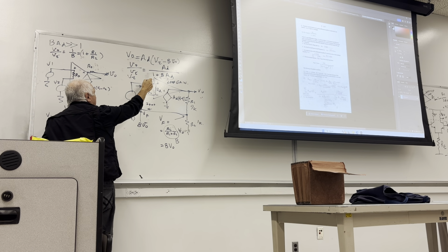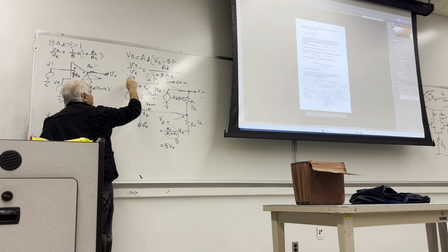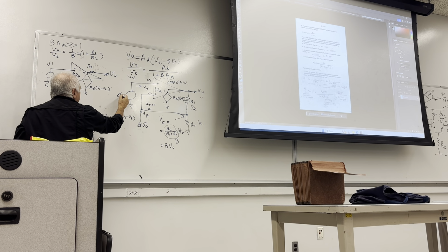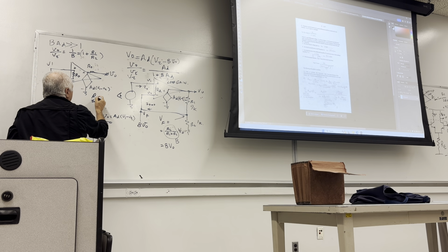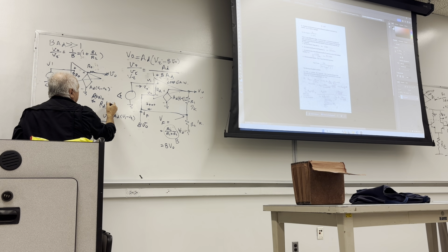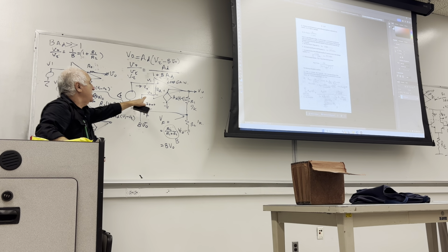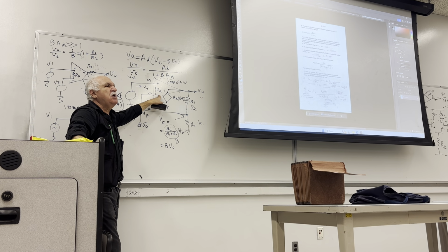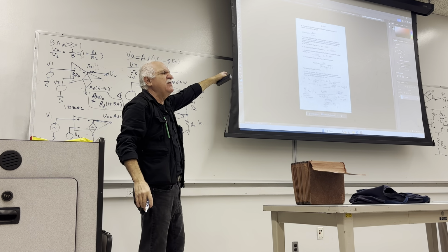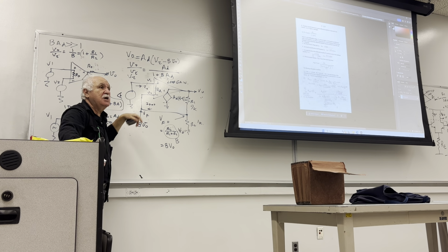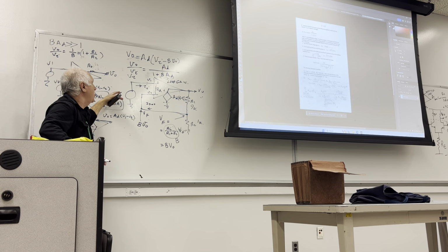And if you calculate V1 minus V2 and you divide it by II, it is possible to show that the input impedance R in with feedback will be equal to RD multiplied by 1 plus B times A. Then you will say, now check this out. You're making an amplifier, RD is 10K, like this one we had. It was 7K. Do I have to worry about having a low input impedance amplifier? Answer is no, no worries.